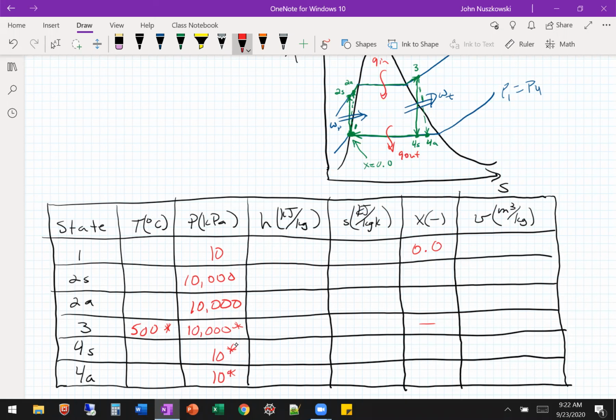State 3, because as mentioned, it was superheated when we checked this out. So that means that's also fixed, since pressure and temperature are independent in the superheated range, where we have 2 independent intensive properties, and our state is fixed at state 3 also. Okay, so we can get anything we want. I don't like to fill in everything just because it's a lot of information. I'll fill in just what we need as we need it. I don't want to just grab a bunch of properties because it could end up being time consuming getting more properties than we need. Okay. All right, so we're there.